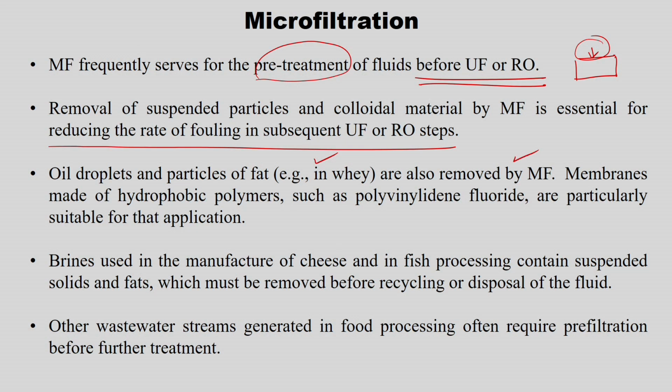The membranes made of hydrophobic polymers such as polyvinylidene fluoride are particularly suitable for that application. Which application? Oil droplets and particulates of fat. So, when we want to remove these, we are supposed to use hydrophobic polymers, which is nothing but polyvinylidene fluoride. So, that as a membrane we can use in the microfiltration technique.